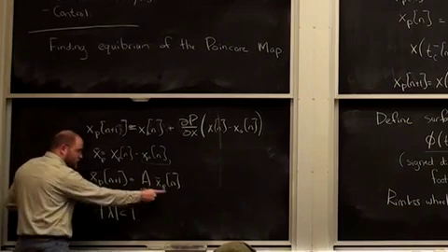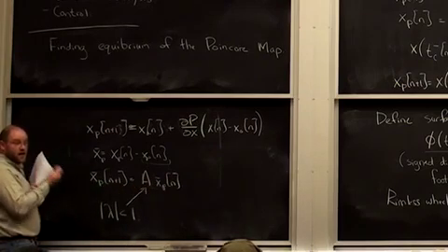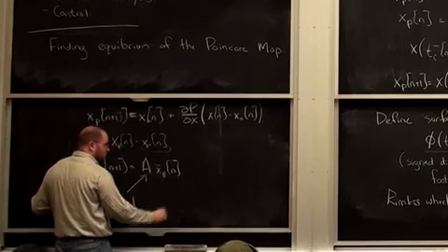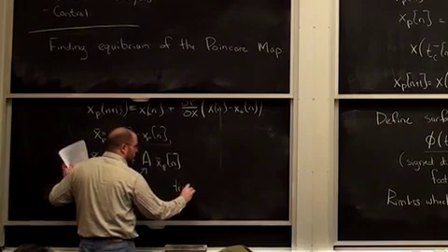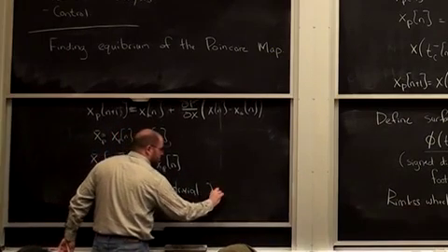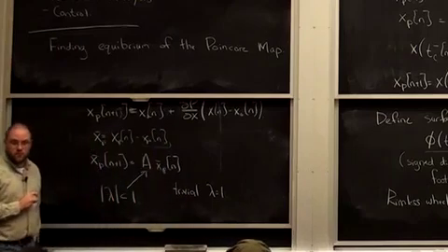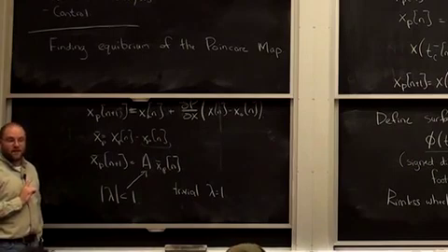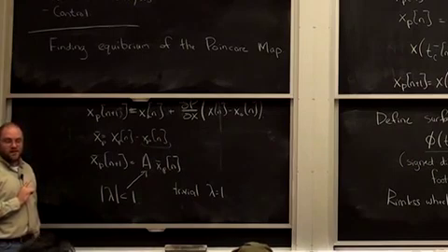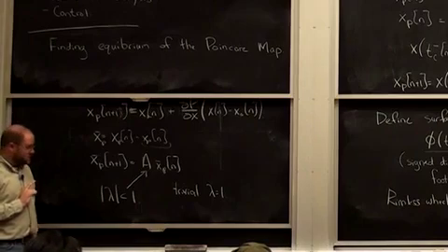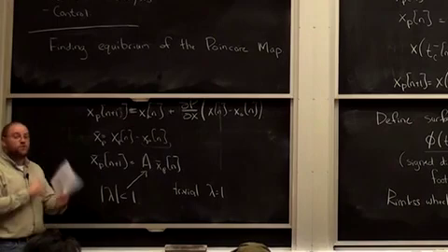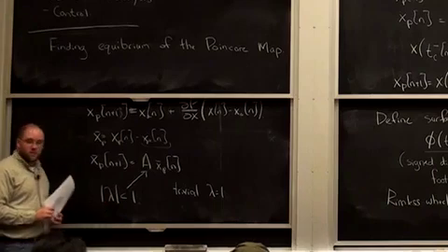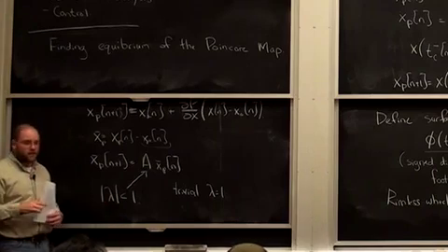In the way I've written it here, if you look at A that comes out of a stable periodic oscillation, there's always a trivial eigenvalue of 1, which doesn't degrade the stability of the system. What does that eigenvalue correspond to? If I take my stable rimless wheel, compute A, and take the eigenvalues, I see that the system is stable and goes to my nominal thing.